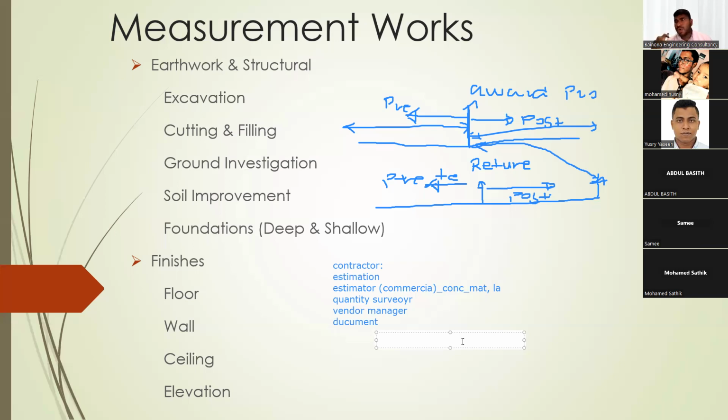Similarly, the quantity surveyors work on the quantities. As I mentioned earlier, together they put the rates that came from the estimator and the quantities that come from the quantity surveyors, and they make a bill of quantities. A very important thing is here. Now you have a material price, you have labor, you have plant or machineries. And interestingly, you need to add overhead and profit.